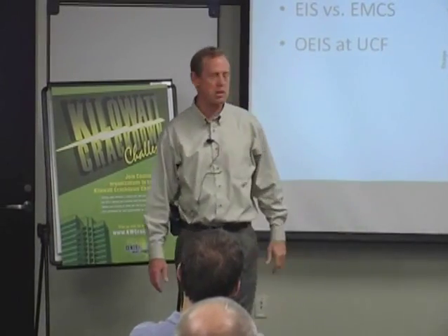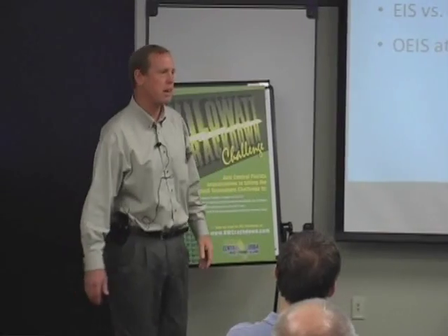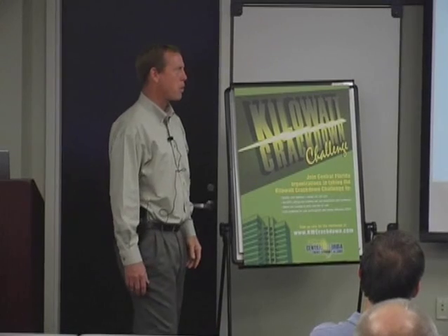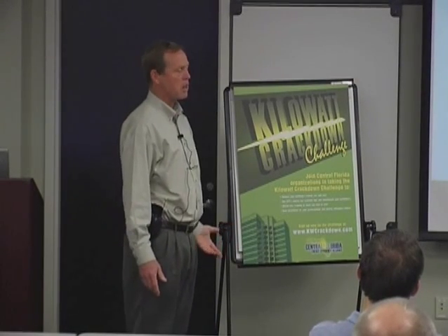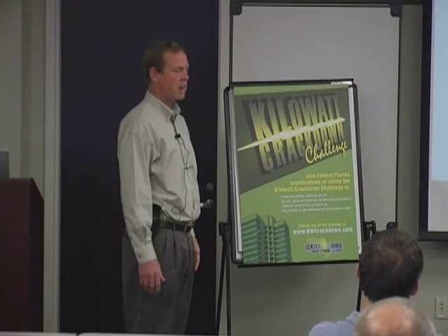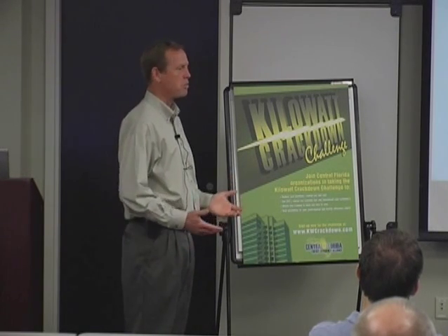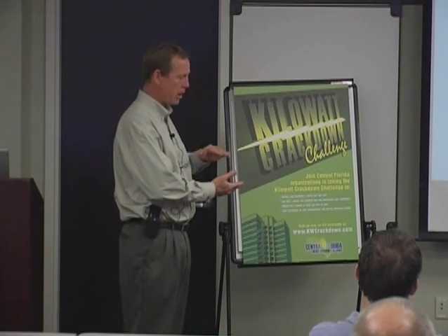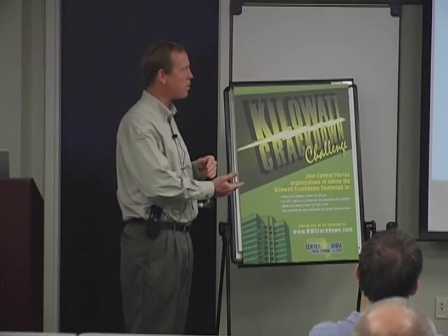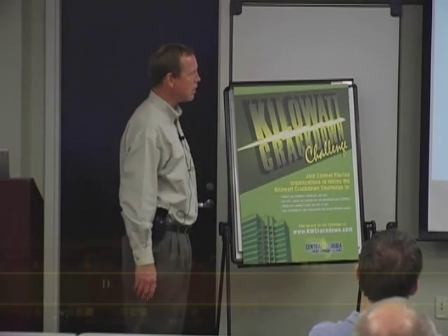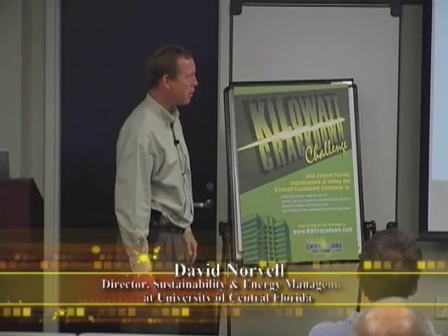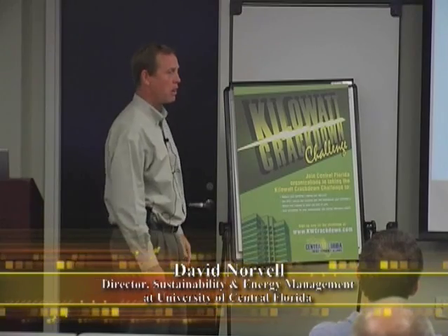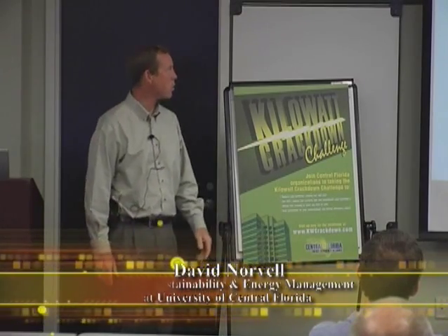Anyone know what might be happening at 7, 8 a.m.? Why would we have those spikes up? Yeah, it's probably a schedule thing, right? The building's becoming occupied. It's got an automation system in it, and the schedule's saying that it's almost time for class to start. We need to go from an unoccupied set point to an occupied set point. So at that time, I don't have the date there, but it must have been some kind of winter day when it banged on the electric reheat to get the space temperature right.